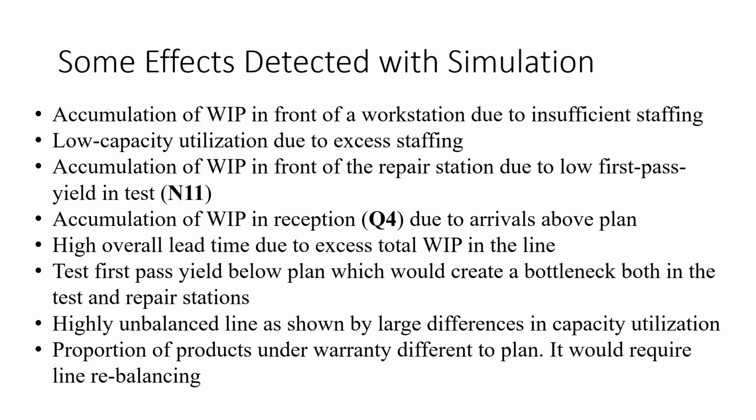These are some of the effects we can detect in our simulation. Accumulation of WIP in front of a workstation due to insufficient staffing. Low capacity utilization due to excess staffing. Accumulation of WIP in front of the repair station, due to low first pass yield in test, N11. Accumulation of WIP in reception, Q4, due to arrivals above plan. High overall lead time, due to excess total WIP in the line.